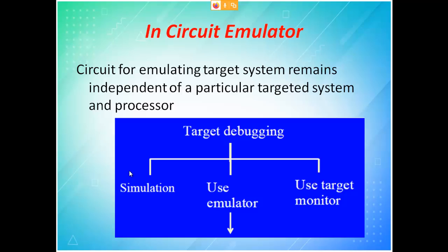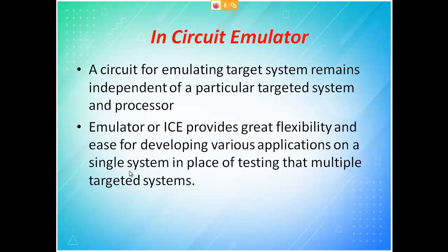In simulation, you don't have hardware, you don't have anything, you just simulate with the help of a circuit. In emulators, you have hardware, but that is not the real hardware; it is just emulating how that particular hardware will behave. Then you use your target monitor. All these three combined, then the final target debugging work is done. So in the in-circuit emulator, target systems remain independent. That is what I told. The emulator or ICE provides greater flexibility and makes it easy to develop various applications on a single system in place of testing multiple target systems.